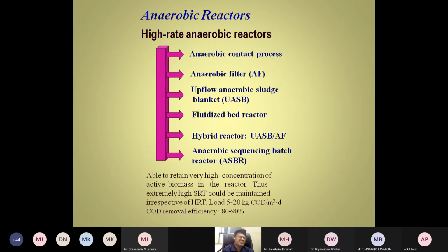So sludge management will become much easier if you use sludge digesters. If you have visited a sewage treatment plant, all the sludge generated from the activated sludge process goes into the anaerobic sludge digester, where due to anaerobic reaction, the sludge quantity becomes very less. Sludge is what? Biomass is what? It is also organic. Everything is organic, you know. Biomass is also organic.